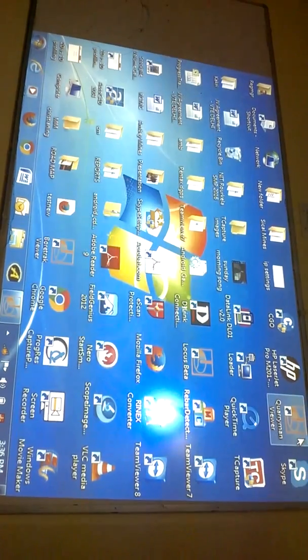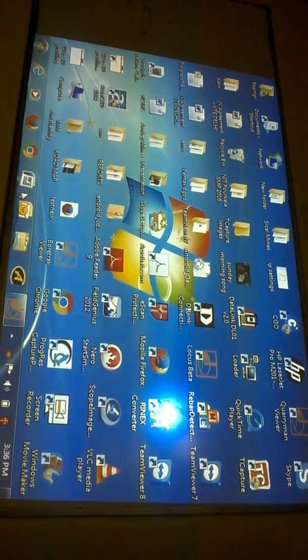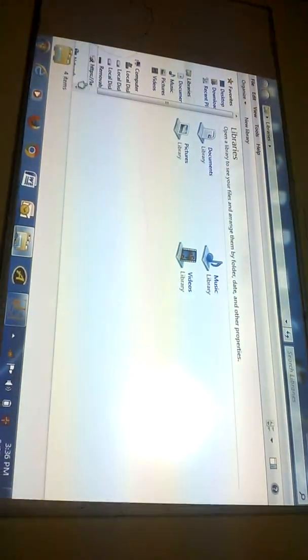Now the file has been saved in the pen drive. I go to the pen drive, pick up the kit file. This is the PTS file which has been saved. So now if I open this, it is a CSV file, comma separated value. You see the values here: X, Y, Z of that coordinate point, and this is the intensity of the laser.